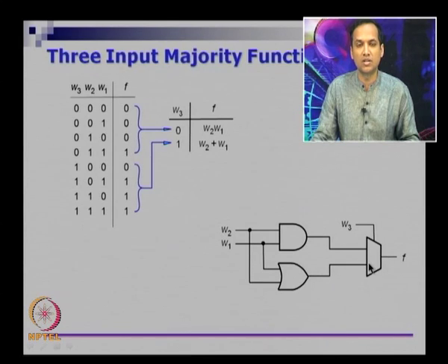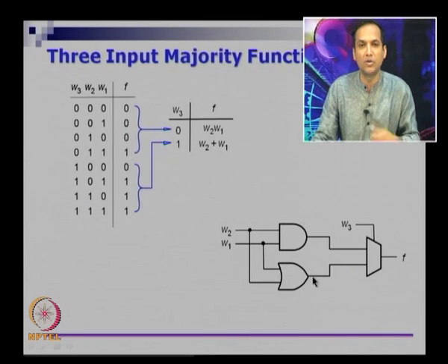So what I am trying to show here is you do not have to use 2 to 1 muxes always to do this. In this example, if I had an AND, OR and a 2 to 1 mux, it is enough to design this circuit. I do not have to ask for 3 2 to 1 muxes or 1 4:1 mux and so on. I do not need it.